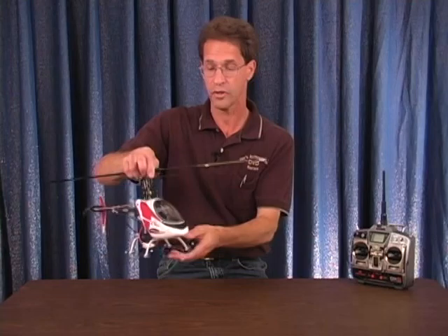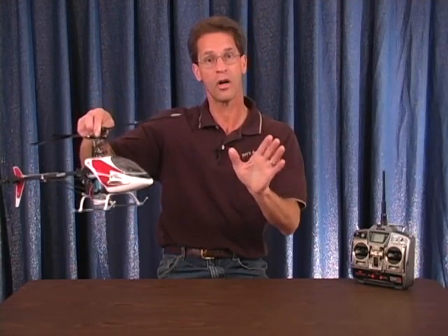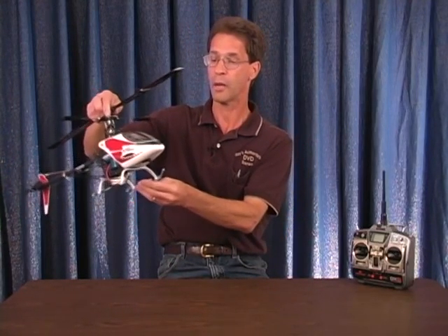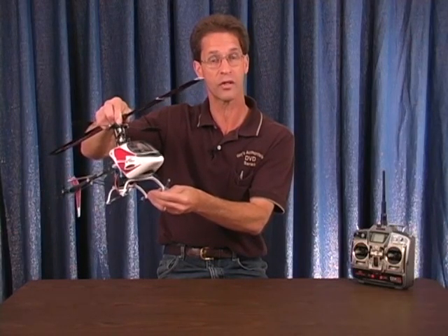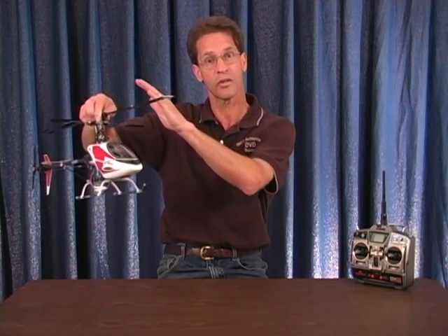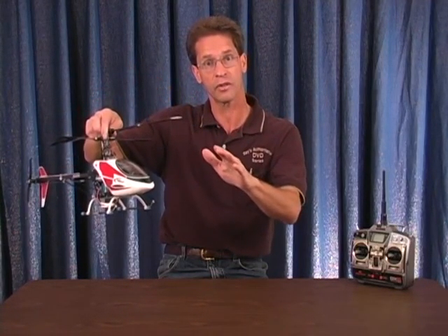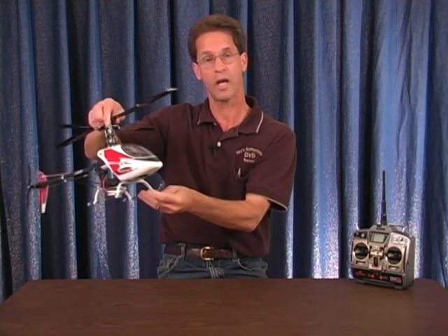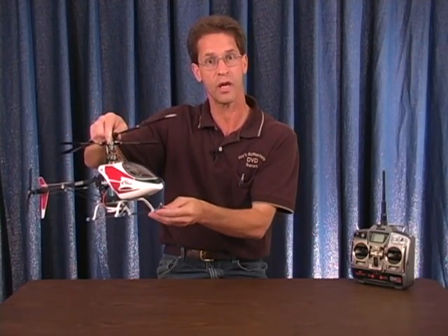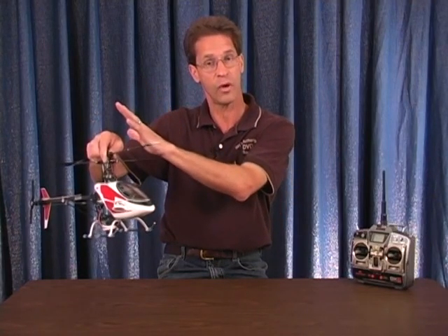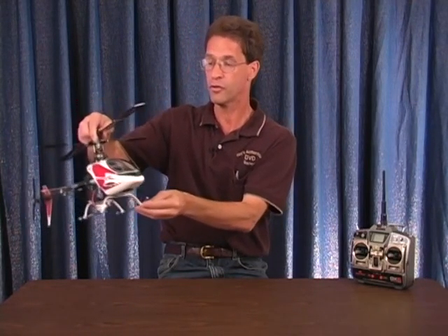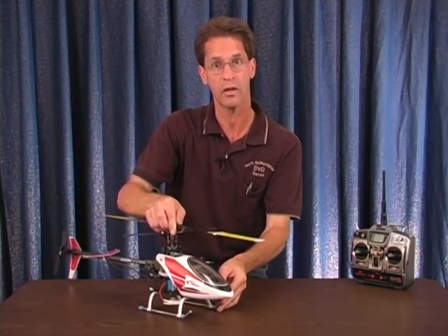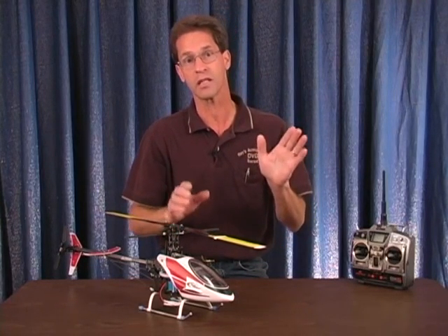Now, when you do auto rotations from altitude, the yaw isn't as noticeable. The helicopter will yaw about 10 degrees to the right, but then as the tail rotor slows down in the auto rotation, the yaw will come out, or the nose will stay straight. So basically, from halfway down in the auto rotation through the flare and the touchdown will be exactly the same as in the DX7.